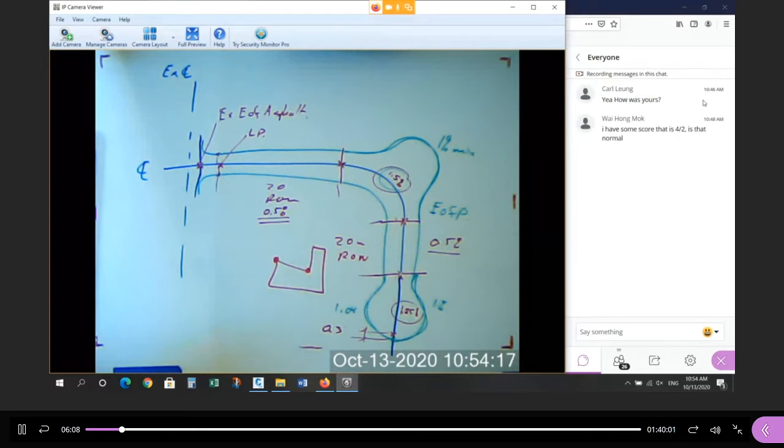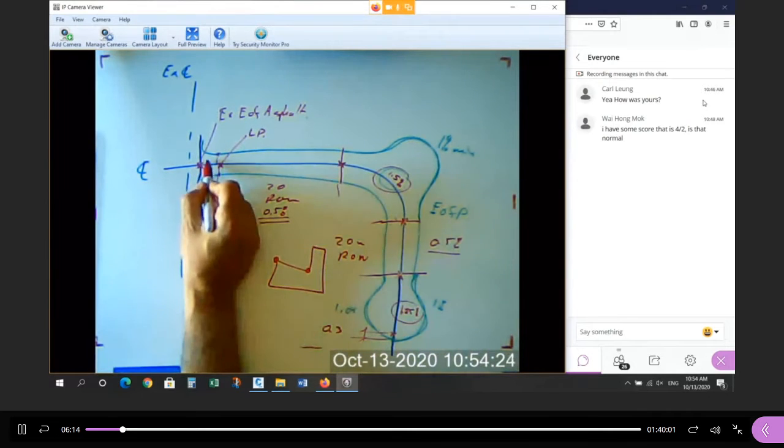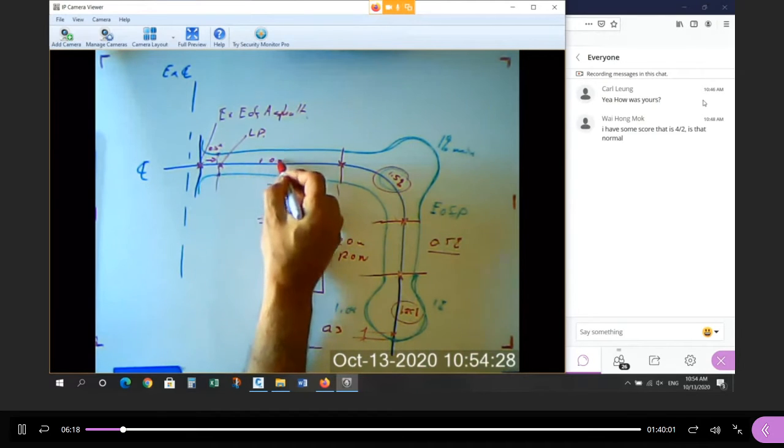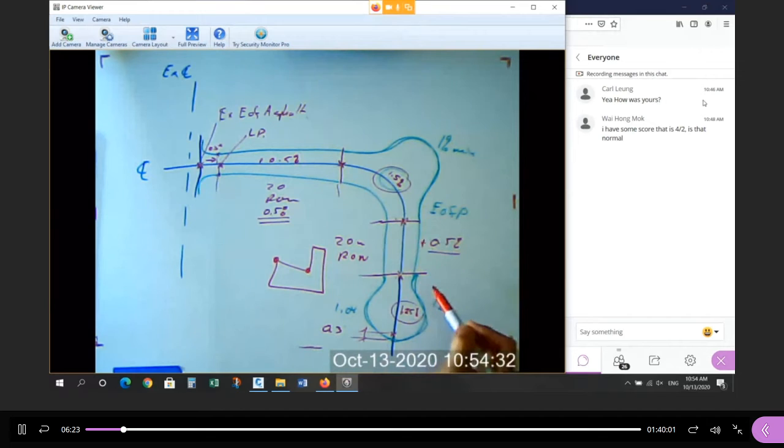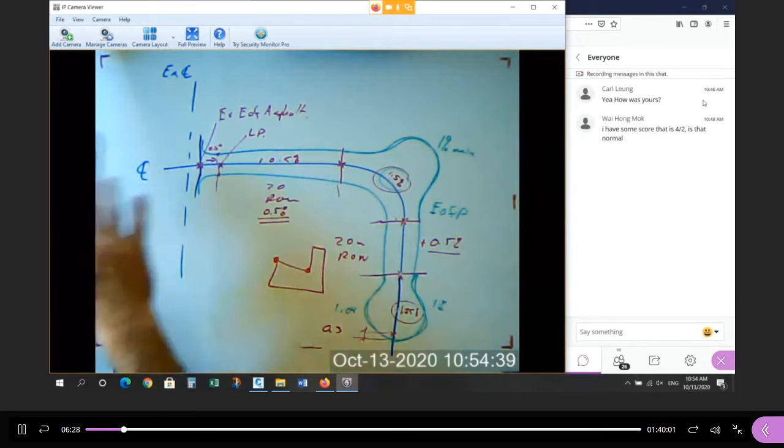And that's all you get, station locations. Then you have to design the elevations for each of those stations by putting in the appropriate slope. And remember, we're going to go down to the low point, 0.5%. Then we're going to go positive 0.5%, then positive 1.5, positive 0.5, and then positive 1.25. Okay, and that was the profile design.